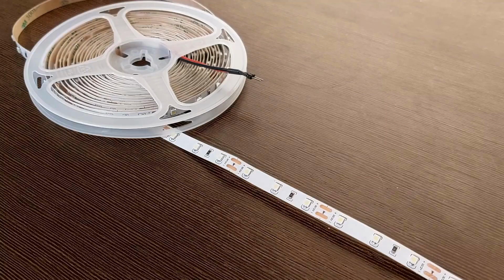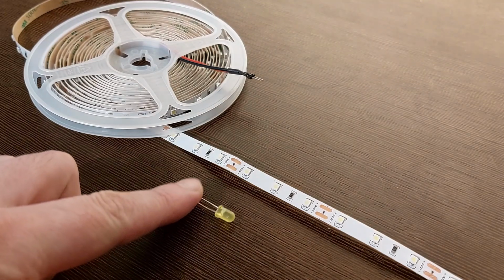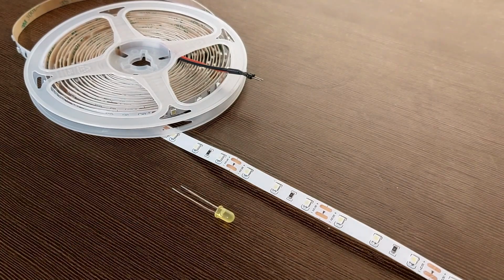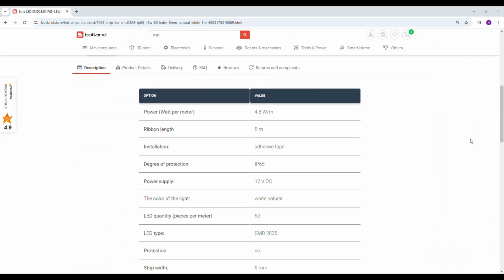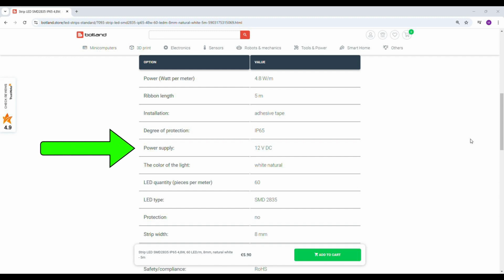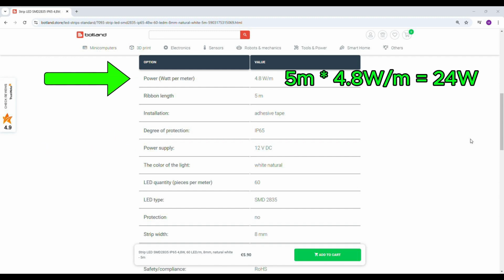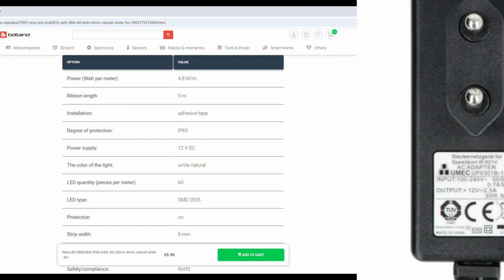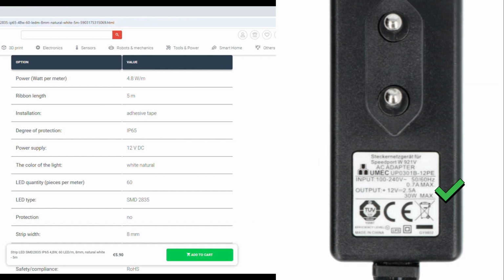One small caveat for a start. Even though such an LED strip looks more complex than a standalone LED, such a prefabricated component is actually easier to handle than a single LED. That's because such structures have clearly defined operating voltage and power, so all you need to do to make it work is to provide a power supply that meets those parameters.